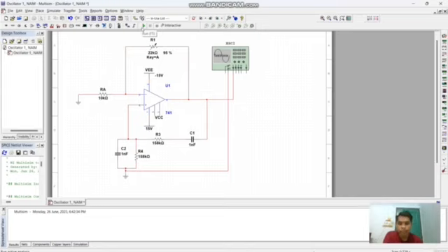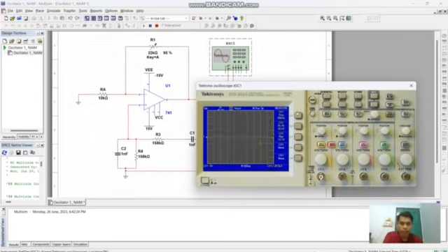So this is my circuit in Multisim. For RA, 10 kilo ohm into the IC 741, for the RF 22 kilo ohm, and I set it at 95%. In the bottom, 1 nanofarad and 158 kilo ohm for the parallel, and the series is 158 kilo ohm and 1 nanofarad. Into the oscilloscope, when I run it, I get the result 996 Hz, 28.2 volt peak to peak, and the maximum voltage is 14.1 volt. And that's all from me.